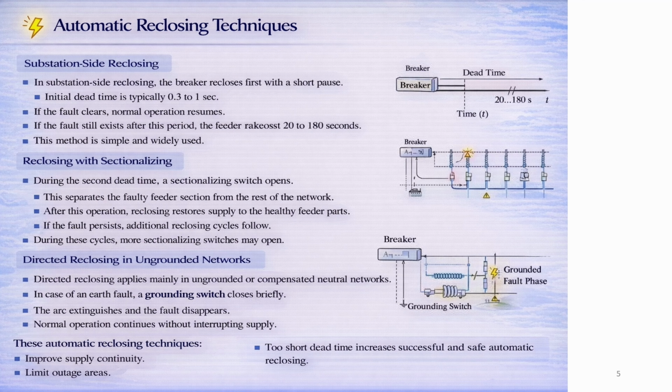If the fault persists, additional reclosing cycles follow. During those cycles, more sectionalizing switches may open. This technique is effective when the feeders include several sectionalizing points. It reduces the number of disconnected customers.